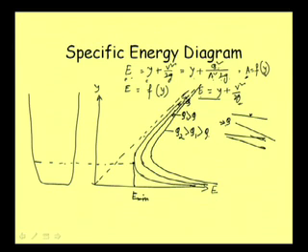So with the increase of discharge, our lines get shifted to the higher side, and joining all these points, here we have our minimum specific energy. This minimum energy corresponds to the discharge Q2, this minimum energy corresponds to the discharge Q1, and this minimum energy corresponds to the discharge Q.